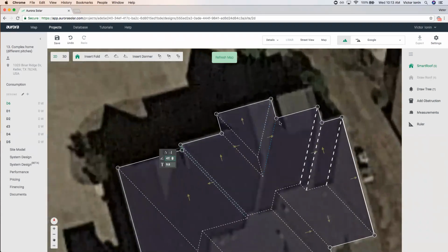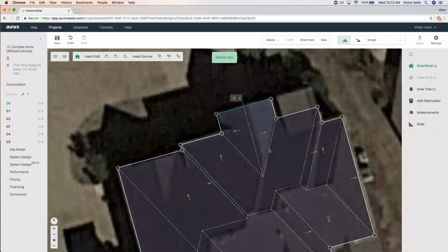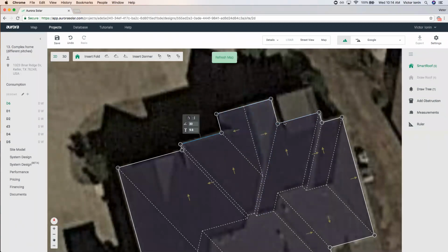And here's another cool thing I can show you again. You can see that this dormer shoots up kind of all the way to the ridge. And if you remember correctly, when I showed you earlier, you can drag these lines so that this edge line is not in line with this one. And you can actually create that type of feature where it shoots up all the way to the top. Just make sure they're not lined up.